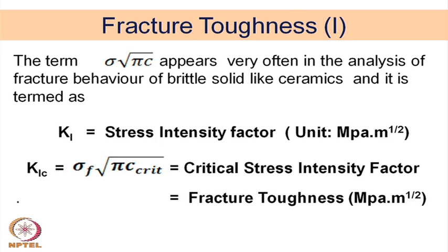So, that is a term, the fracture toughness, which we will use very often, in fact it is used very often to understand not only the crack behavior, but basically the mechanical strength of a ceramic material. Okay. Fracture toughness is one of the most critical parameters we normally consider, how reliable this material will be, how it can behave under different stress fields.